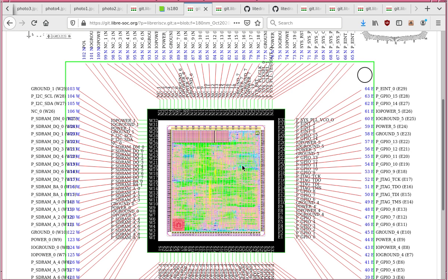So the main things are, you need a boundary scan, and you need the entire code base to understand it, and it routes right the way through pretty much absolutely everything. In terms of the 3 pins, to each of the I/O pads go 3 wires, apart from power and ground, of course: the input, output, and output enable.